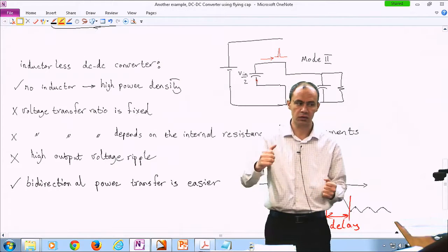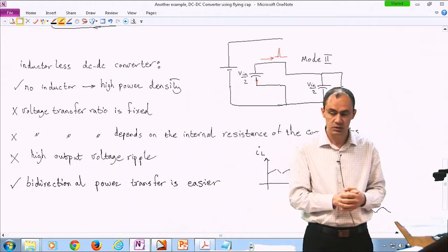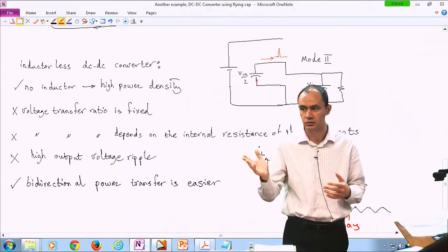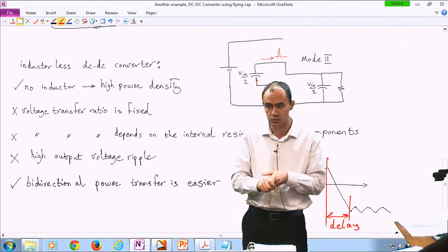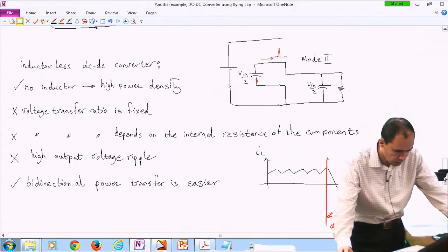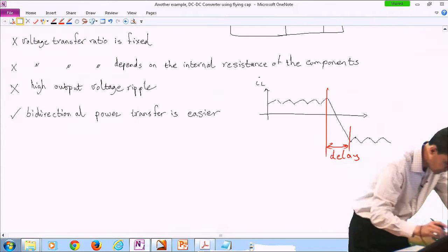Because if you are drawing a huge amount of power from a 12-volt system, then the current is too much, and the conduction losses are going to be too large. So one application that I've seen in a paper is using this topology for this exact application.